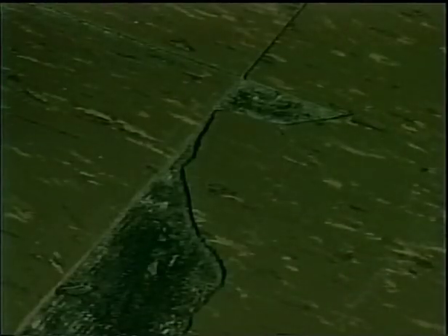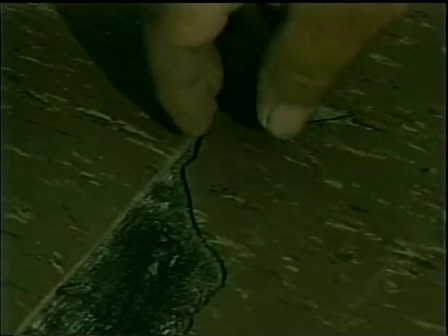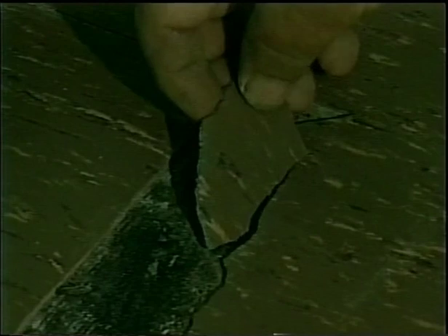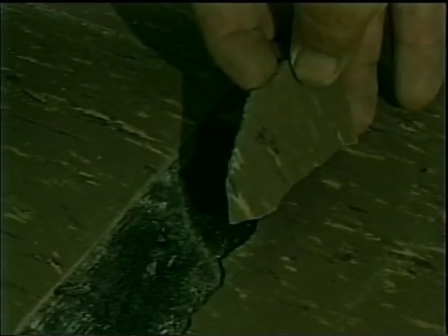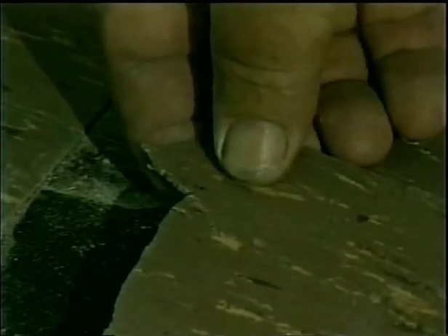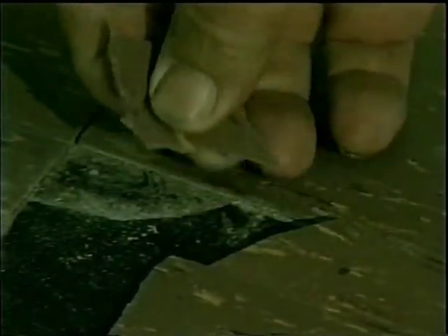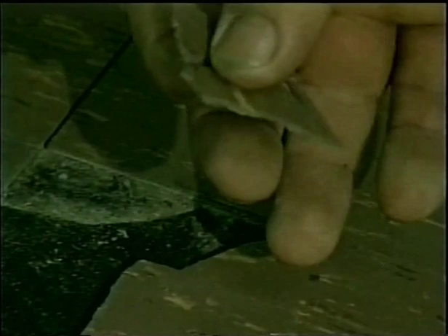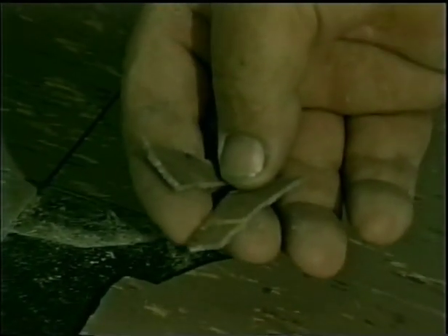Here is a damaged floor tile. Notice that the tiles are no longer sticking to the floor, and some of them are broken. This damage has occurred because of water and physical abuse. The material has broken into several pieces. While the breakage is severe and the water has loosened the tiles from the floor, the matrix that the asbestos is in is not damaged, and therefore the material is still not friable.